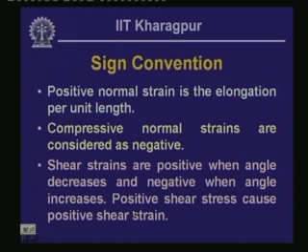Well, now that we have evaluated the strain at a point, if the reference axis is oriented at an angle of theta with reference to the rectangular axis system x and y, we have seen how to compute the value of the maximum normal strain, which we have called the principal strain. We have seen how to compute the value of the maximum shearing strain and the orientations of the principal strain and the shearing strain through the angles theta p and theta s.